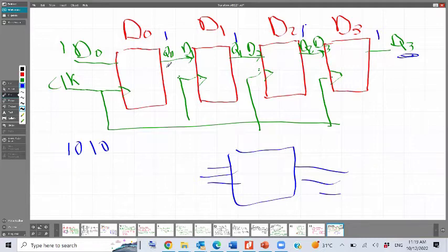Anything that takes values, I have to declare it. I may declare it in the entity as input or output, or I may declare it somewhere else as something else. Would it need to be declared as a signal? Yes, excellent. Since those are input and output, and those are internal, they don't reach the outside world.